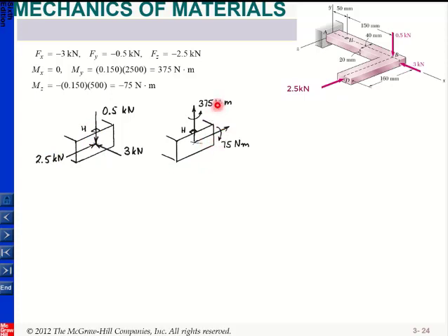And when I look at these two moments, since point H is here at the centroid line, this moment My will not create any stress at point H because it's at the neutral axis. Okay, but this one, it will create a stress, and it's at the top. So you might need a couple of pieces of information. One of them is area, so you can get the area, and since I will use Mz, I also need Iz there.